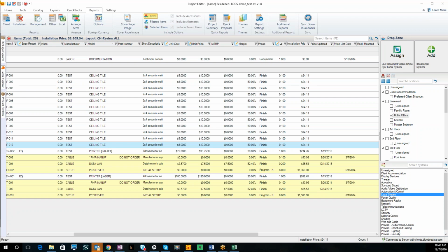Absolutely. One other thing I might add, I think it was Rich Harris, your CAD guy, pointed out to me that if you're creating something unique and you're going to use it in multiple places on a drawing, it's good to push it up to the product database. Then the first time you select it and go for your drawing shape, there's a checkbox that will allow you to use that every other time you drag it out, which is very convenient. Otherwise, every single time you drop it onto the page, you have to go through that whole rigmarole of selecting the shape and putting it in there. So that's very handy.